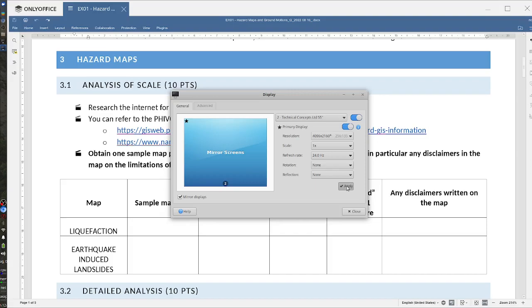Okay, so you just plug in the values of your earthquake magnitude. So in this case, it's 6.2, and plug in the values of your fault distance in kilometers. Okay? And you will eventually get 10 raised to 2.67742853, and you will get PGA in units of cm/s². Okay, so this is also in gals or cm/s².